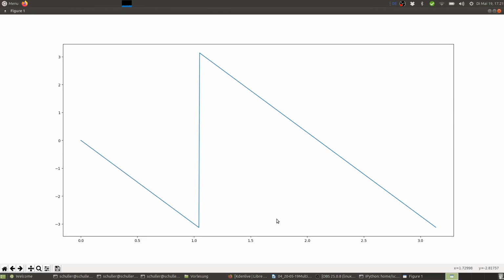So you can see it. Horizontally we have the normalized frequency going from 0 to pi. And now you can see here we have a linear function. Remember, we have a delay of 3 samples. So basically we have omega. When we have 1, then we should have minus 3 for the phase, which indeed we can see here. If I put my pointer here, we can see on the small numbers down here, 1 and minus 3. So indeed we have the slope of minus 3.